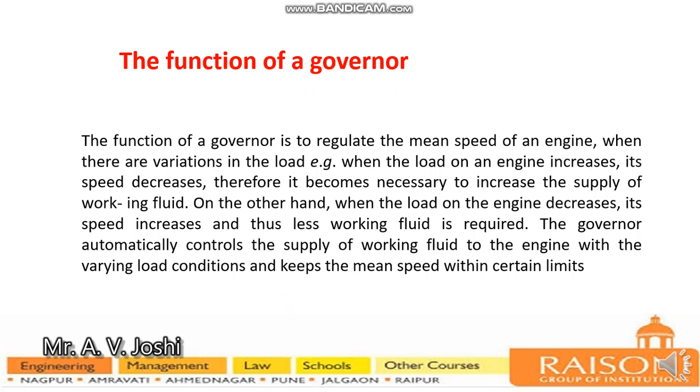On the other hand, when the load on the engine decreases, its speed increases, and thus less working fluid is required. So to maintain an adequate quantity of fluid, we are using a governor. The governor automatically controls the supply of working fluid to the engine with varying load conditions and keeps the mean speed within certain limits.